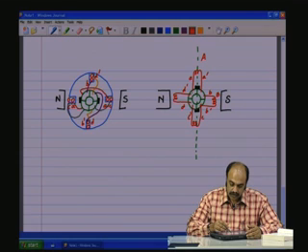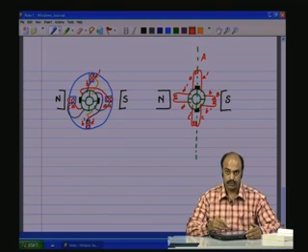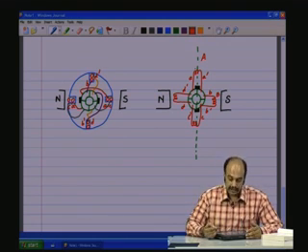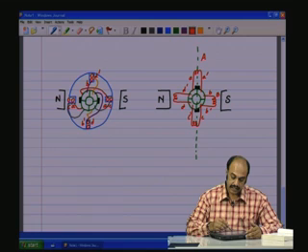So the starting of the coil, you are starting at one commutator segment, the other end of the coil is connected to the immediate next commutator segment. The starting of the other coil is from that commutator segment and ends on the next commutator segment, the next one starts at that same commutator segment, goes to the next, and so on and so forth. So this way the winding pattern for the 4 coils is shown. See that A and C coil will be 180 degrees out of phase,